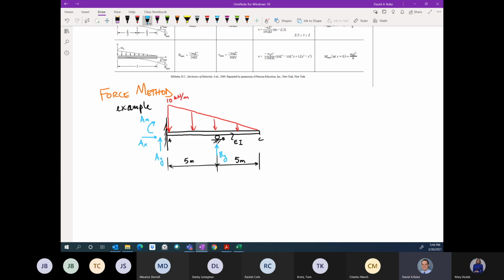And I know that since I only have this one continuous beam, basically, I need only 3 reactions. I can only solve 3 because I can sum forces in the X and Y directions and sum moments, which is actually about the Z axis. So I can only solve 3 unknowns. There's 4 here.